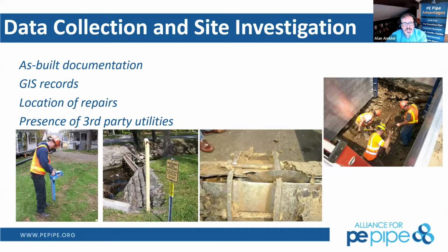So we will look at as-built documentation, GIS records, location of repairs. The reason why repairs are often important to us is that a repair change, either a change in material type or a heavy duty repair fitting, oftentimes cannot be burst through. And so we want to know where those are and what is required to get through that as well.